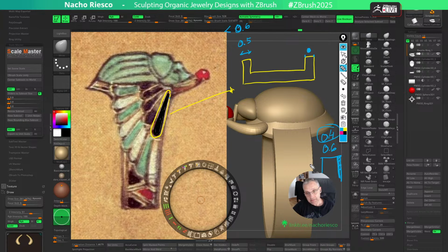So in conclusion, it's difficult to give you one single number, depending on the kind of design you are manufacturing. But probably the objective for this thickness is going to be less than half of a millimeter, just to keep this as thin as possible. But your 3D file is going to have more than half a millimeter. Maybe 0.6 or 0.7, while 0.8 is going to be too thick. Let's see, as we go further with this design, how far we can go with the thickness, because the final thicknesses are going to be obtained during the manual processes.